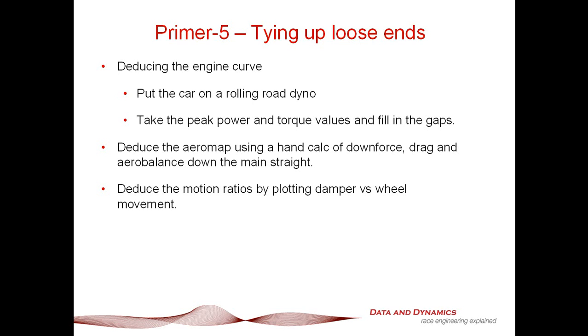Now, in terms of starting off with the aero map, this is something I've spoken about in a number of different articles on the ChassisSim blog and also on Racecar Engineering. But to get going, what I would recommend is that you do a hand calc of downforce and drag and aero balance at the end of the main straight. That's always proven to be a really good yardstick to get a vehicle model up and running.